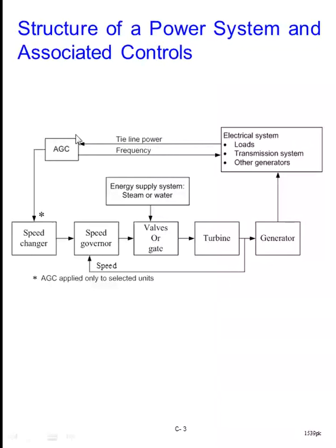All right. To the AGC, it is again feedback to the governor part here. So this is a secondary loop here. This will be the secondary loop. So you have, this is your primary loop, and this will be your secondary loop, the second stage of control, you can say, or the supplementary control loop here. This is clearly presented in this slide from the previous one here.